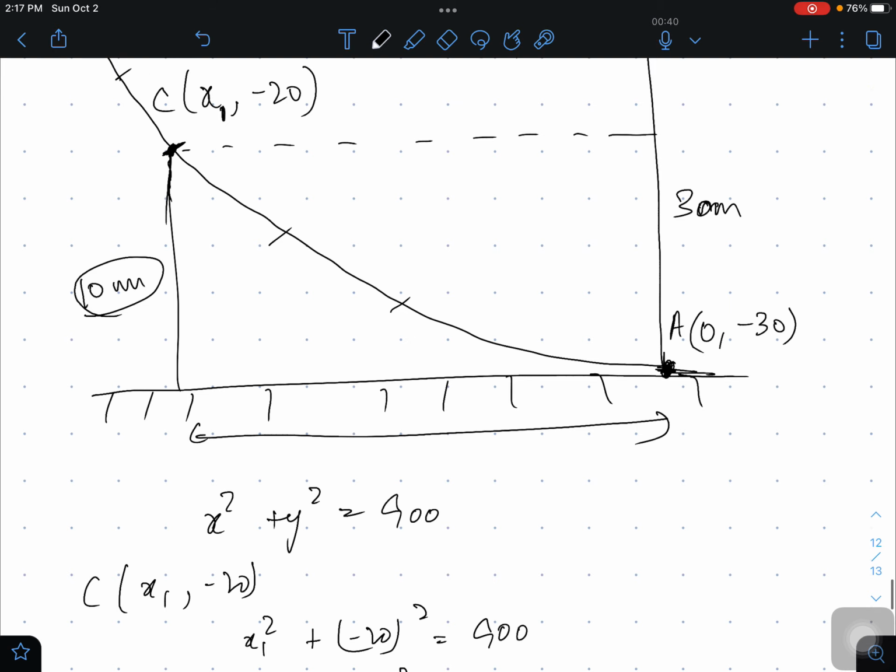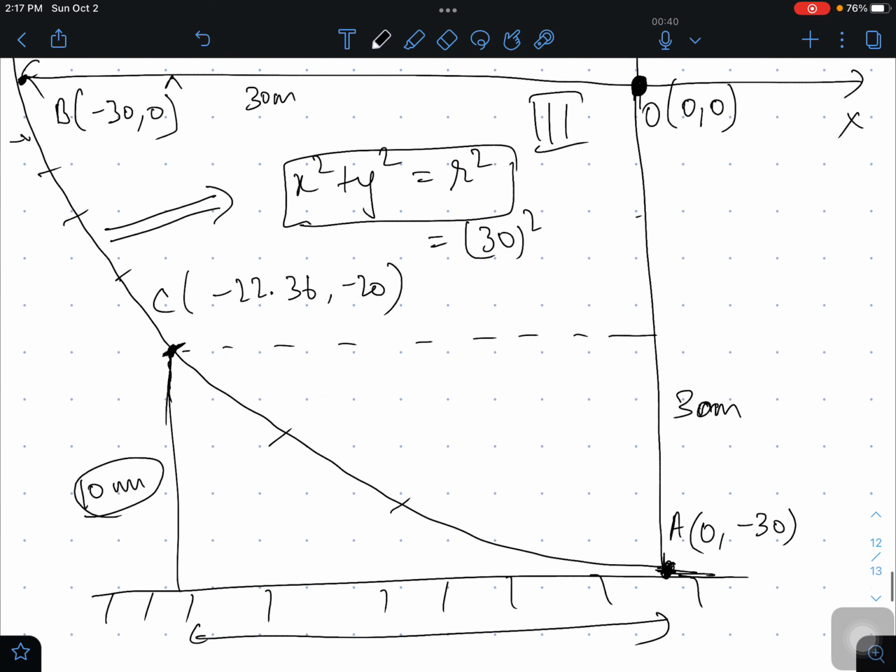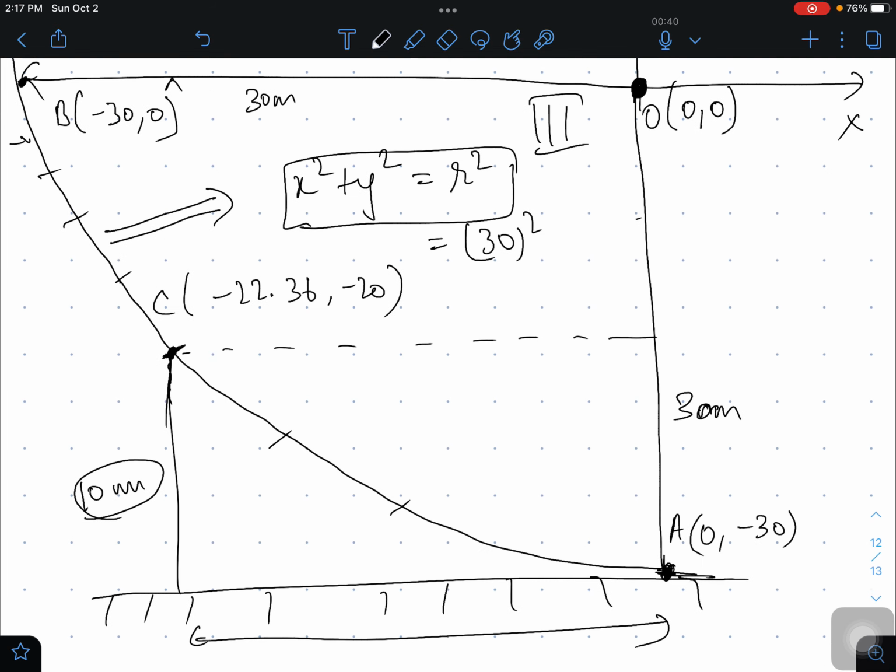So now you have got this value. I will now write down the value of point C. It is minus 22.36 comma minus 20. Now we know this distance from this line, it is minus 22.36. Now we know that there was an equipment which we were thinking of, let us suppose E1, which is protected, and it is at a distance of 2 meters and this dimension was 1. So we will find the worst case, that is this edge point.